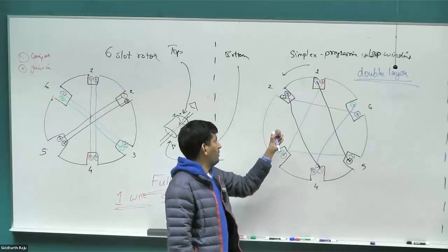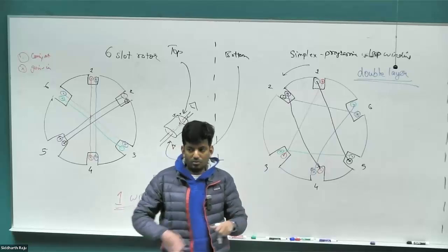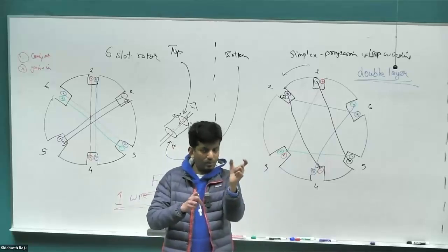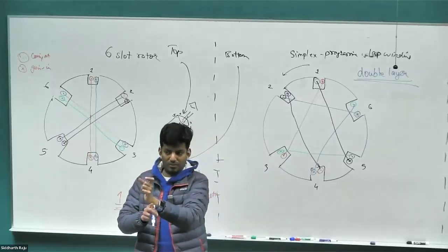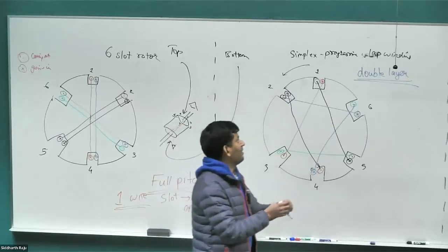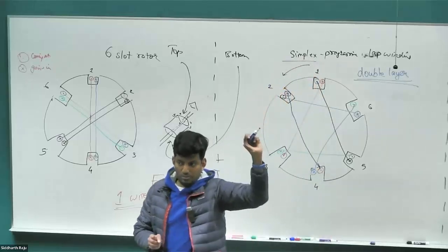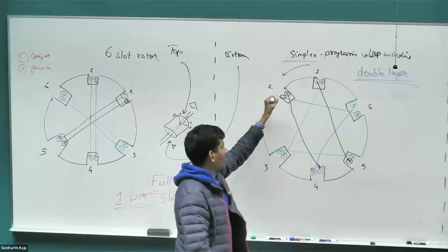Right? In that case, what would then happen is these two would have to be in such a way that they are very similar voltage potentials. So you would have a very large brush that would slide past two commutator segments at once. So it gets a little bit trickier. And that would be, instead of simplex, a duplex winding. All right, those exist too. But in our case, we are looking at a very simple case.